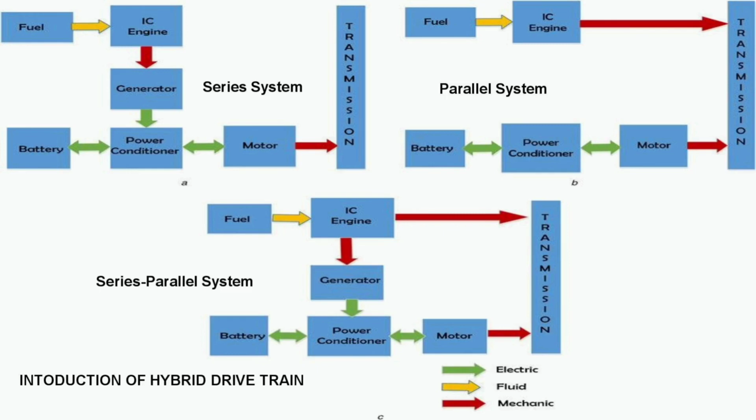And coming to the series parallel system, in the series parallel hybrid, the configuration incorporates the features of both series and parallel hybrid electric vehicles. However, this configuration needs an additional electric machine and planetary gear unit, making the control complex.